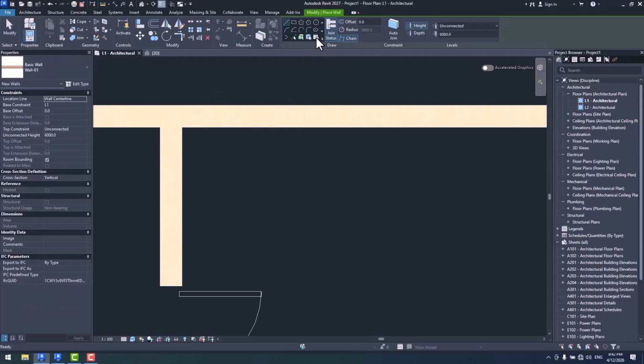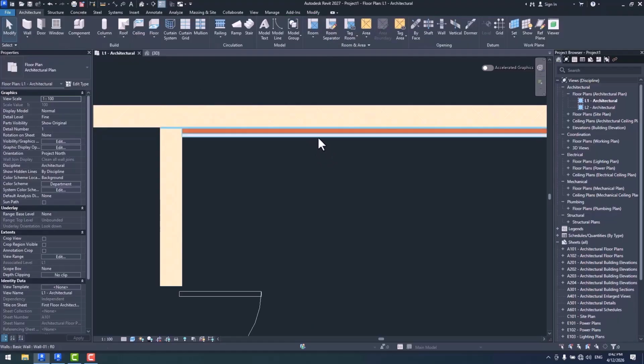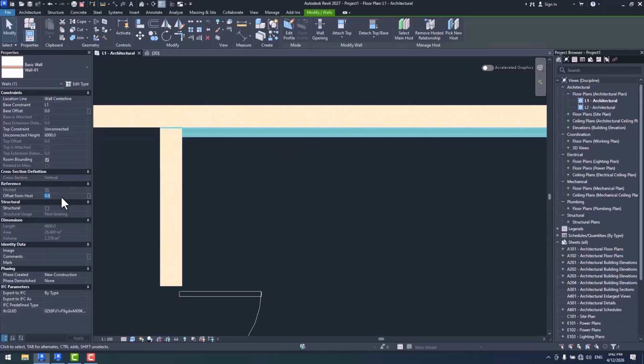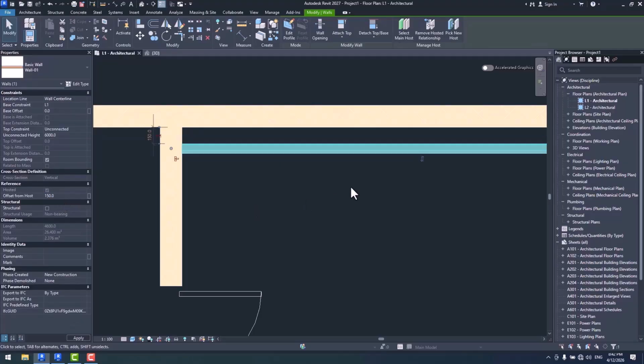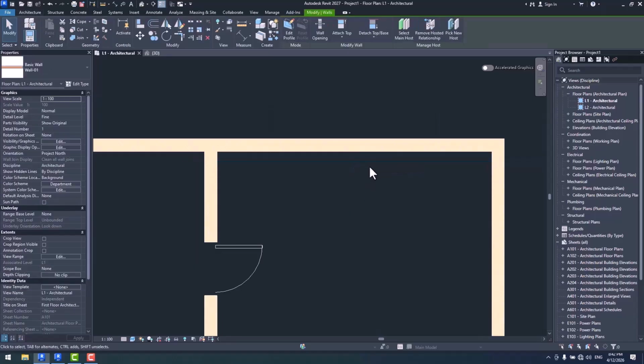After clicking on wall, then place by segment, we need to select hosted walls. Then we should set the wall first, and then after setting it, we would be able to specify the offset however we like. So I kind of misled you guys. First we need to set the wall, then specify the distance in between them.